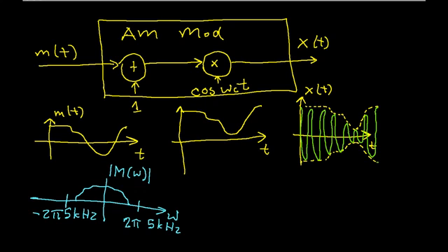Now this is how AM radio actually works and why the sound quality in AM radio is not great. Sound signals often have meaningful information up to about 20 kilohertz, and have to be low-pass filtered to fit into a 5 kilohertz bandwidth for AM radio.